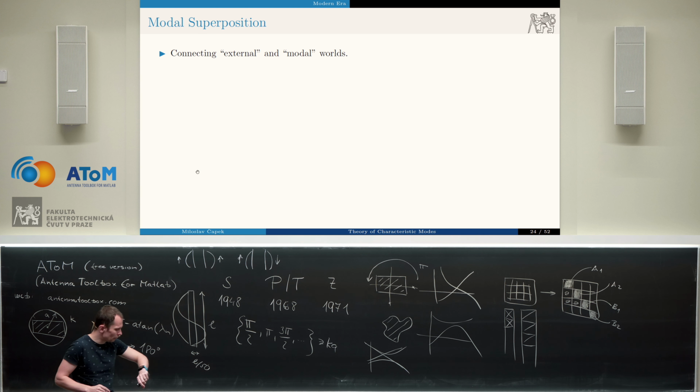And this is actually bringing me to the second part of this talk, that we have already our code implemented, verified, we are able to calculate characteristic modes. But at the end, as electrical engineers, we would like to do something with them. And the last step is that we will really connect an excitation somewhere. That means that we will perform a superposition of all the modes together.